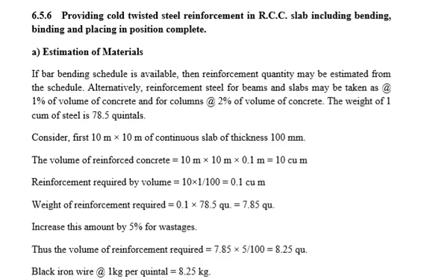It is not available as per your requirement. So we have to cut, we have to overlap somewhere. In cutting and overlapping, some amount of steel is wasted, that is up to 5%. Clear? Last, for binding 1 quintal steel, means 100 kg, we require 1 kg black iron wire.